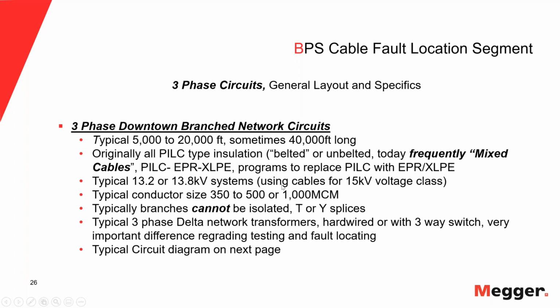But what's really very different about these circuits is they have typical branches in them. And these branches, in many cases, cannot be isolated. They are hardwired T or Y splices. And that makes fault locating a totally different ballgame.